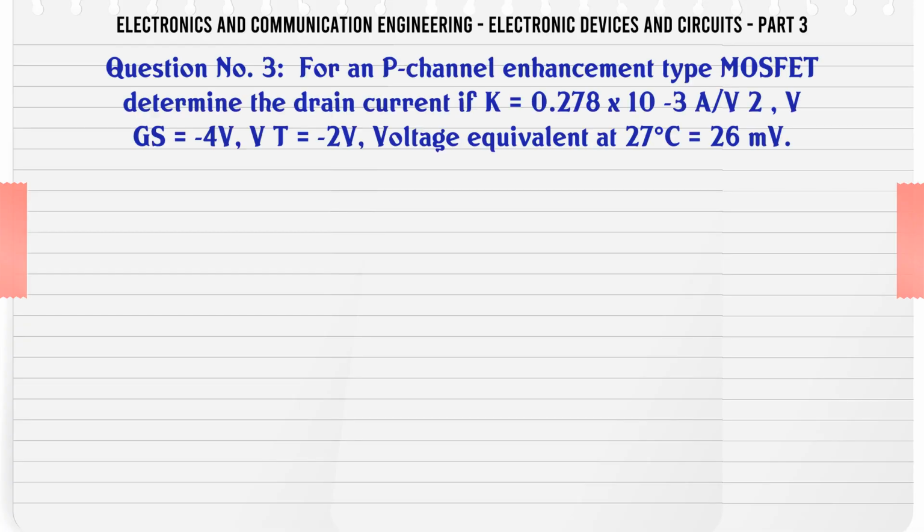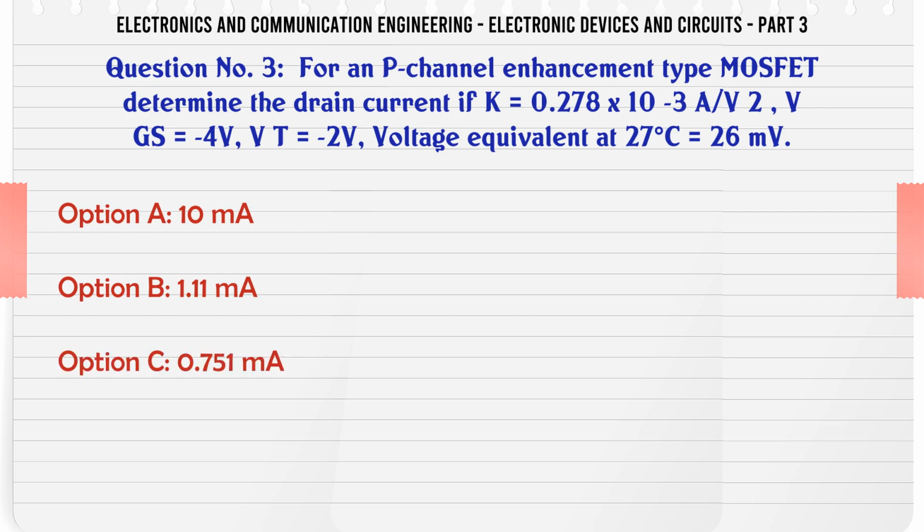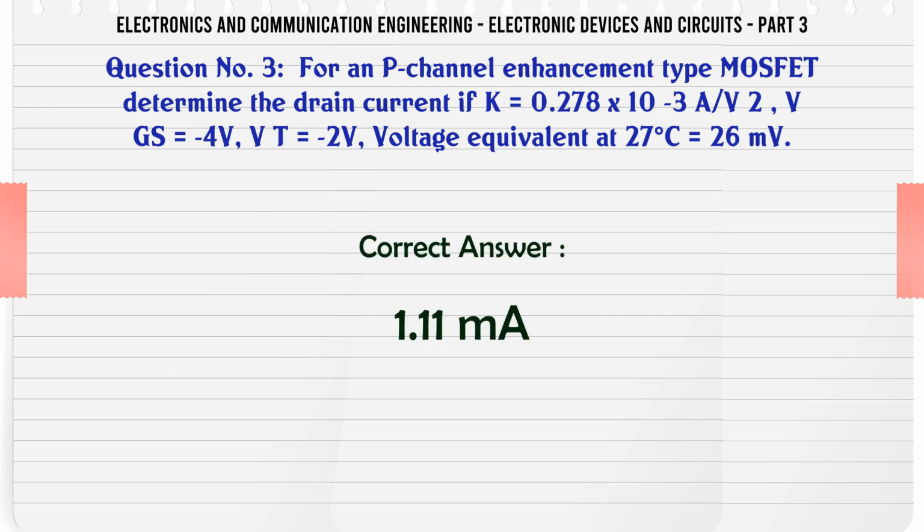For N-channel enhancement type MOSFET, determine the drain current if K = 0.278 × 10⁻³ A/V², VGS = 4 V, VT = 2 V, voltage equivalent at 27 °C = 26 mV. A. 10 mA, B. 1.11 mA, C. 0.751 mA, D. 46.98 mA. The correct answer is 1.11 mA.